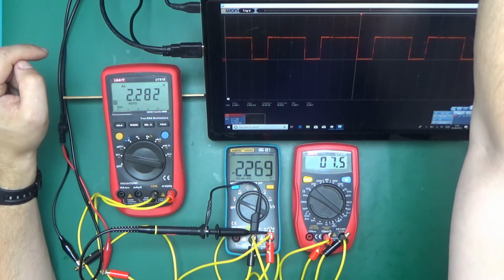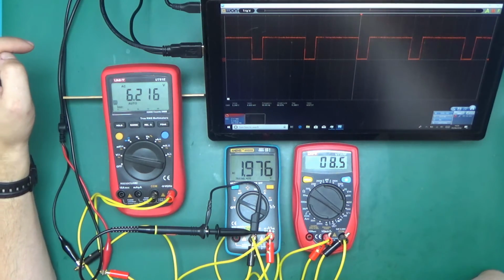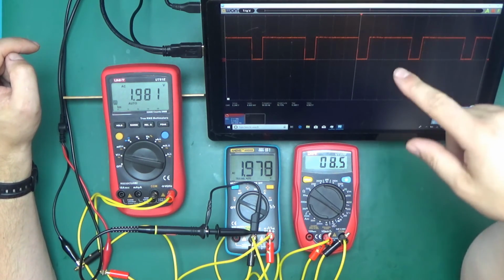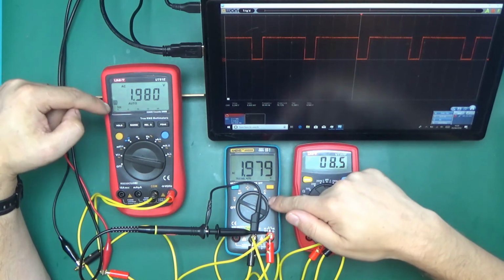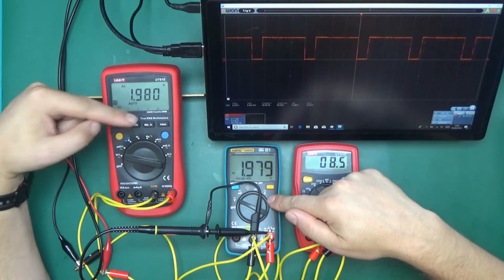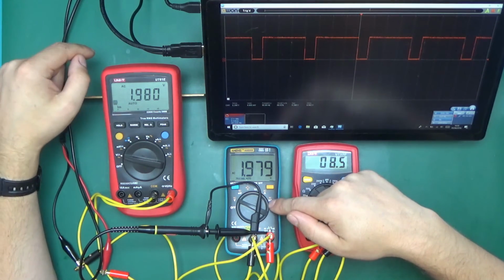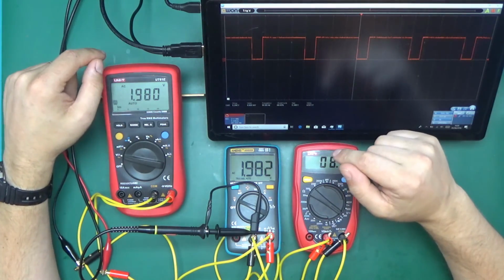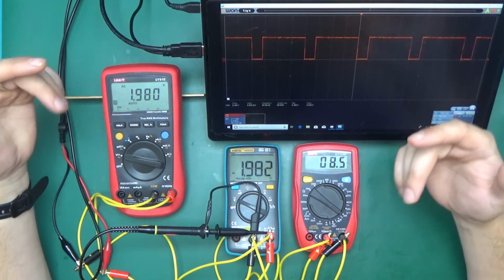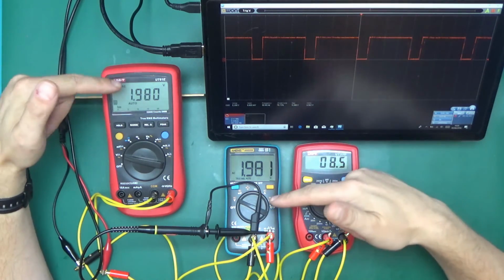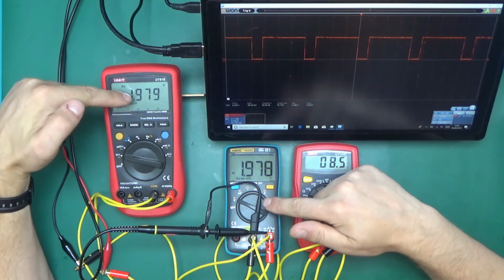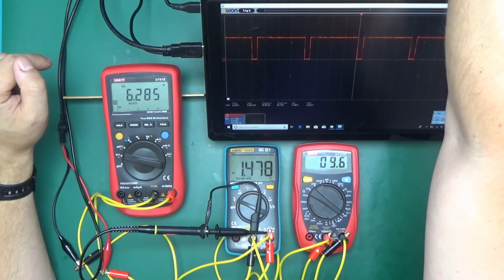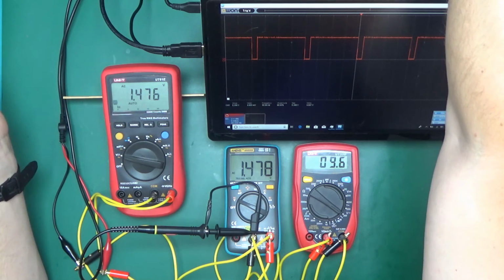Let's keep going. 70, 80%. 80% of a 5 volts amplitude positive square wave, that should be 4 volts. But we've got 1.98 on both of those, and to me that's not the true RMS value. Maybe I am doing something wrong. Let me know in the comments, but from what I understand about true RMS and what it should be, this is not right. This should be 4 volts, not 2. 90%, that should be 4.5 volts, but we get 1.5 on both of them.